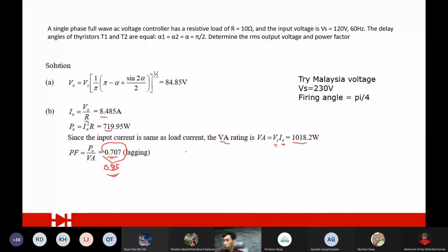All right. So where am I? Oh, okay. Power factor. All right. Like I said, if you are using this AC controller, that will actually distort the sinusoidal waveform of the output. You eventually need to be aware of two power quality issues. One of them is the power factor, another one is the harmonics.